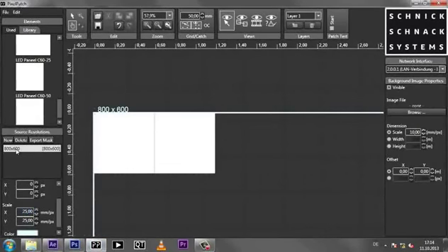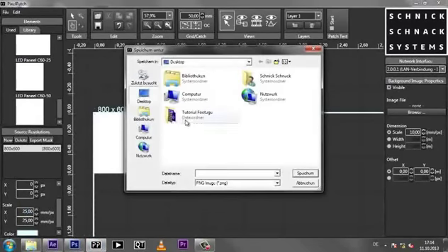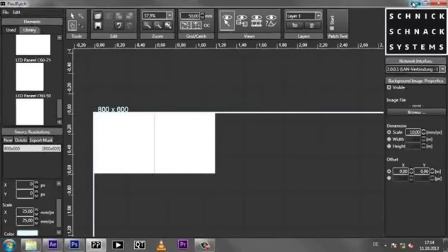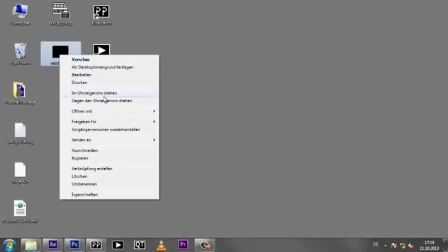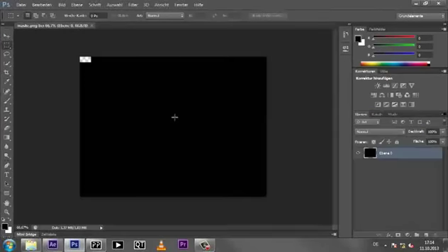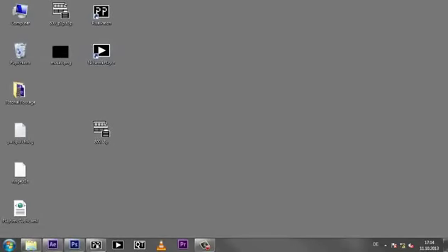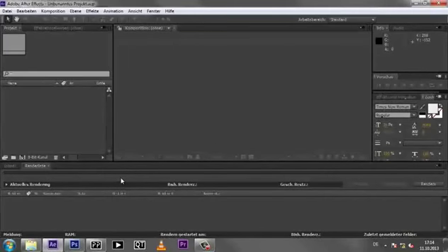So what I can do in the PixelPatch software is right click here on this resolution and say export mask. So I do this now. So what it does now is write me a PNG. And this, I open it now in Photoshop to demonstrate. This is basically a black PNG with a small transparent part. And only this part, these few pixels, are the part that are visible on our LED panel in reality. And this mask I want to now import into my composition tool.